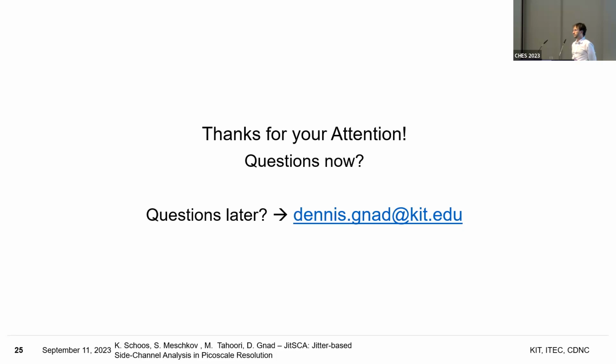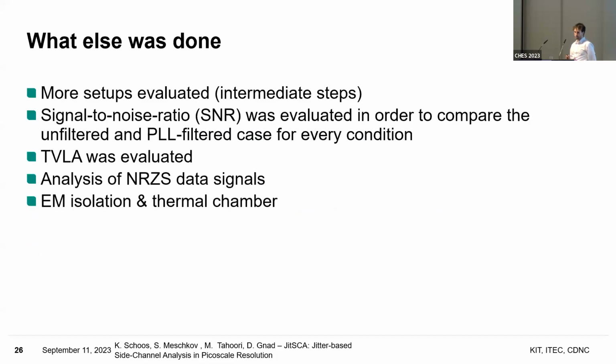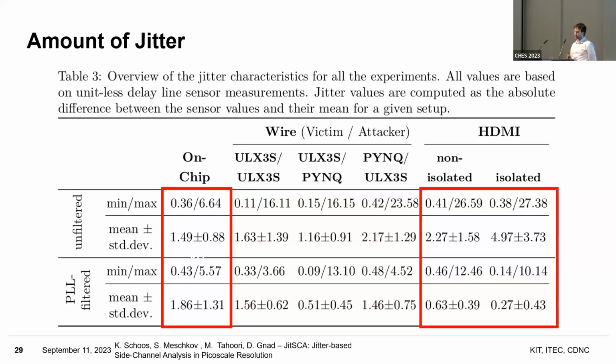My question is related to the amount of jitter that you have seen. Could you somehow measure how large the jitter is? Because I'm a bit concerned: if you give the clock from one board to another board, because these two boards need to communicate with each other, and the jitter is very, very high, then they probably cannot communicate very well, because there might be some race, unless you do some other customized things to deal with the jitter from one board to another. You may solve this, but if the jitter is very large, you may get this problem. But then how large was this jitter that you have measured, and you get the relation between this jitter and the amount of power consumption of the source board?